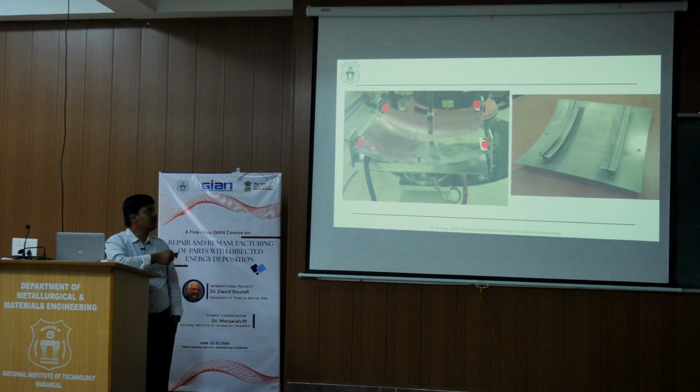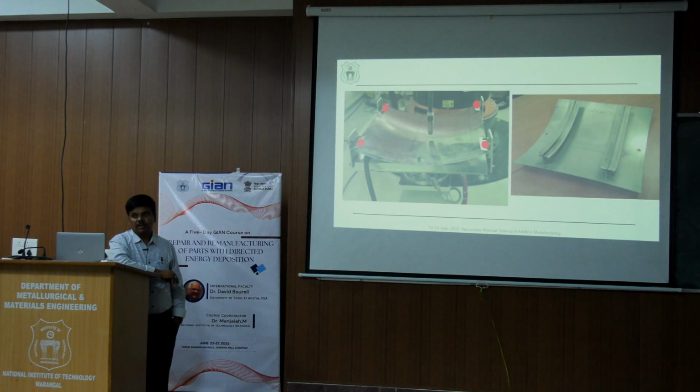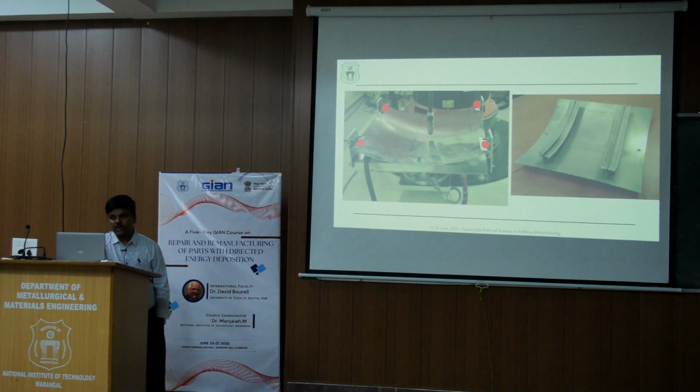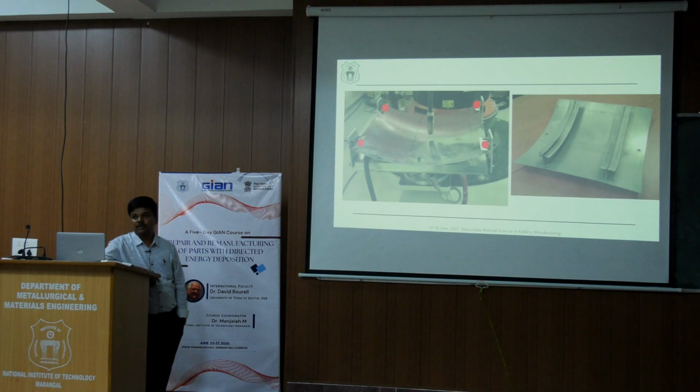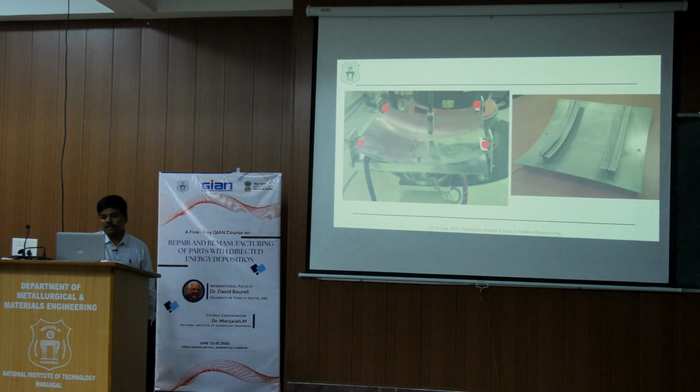For this, we needed to change our path planning. Earlier, the linear path planning was not suitable for this kind of component. Then we tried non-linear path planning, and there were no delaminations in the plate or the deposited parts. We also made several holes to distribute the heat accumulation in the parts.